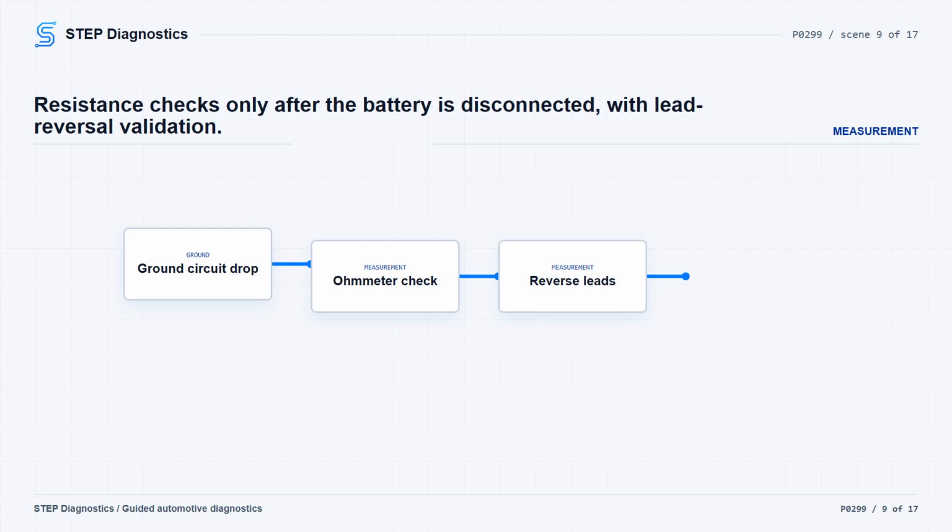Use an ohm meter accurately only if the battery has been disconnected. For most small diameter, 18 gauge and smaller, wires, expect less than 2 ohms. For most wiring harness circuits, also expect less than 2 ohms. A standard DMM ohmmeter's low resistance resolution is approximately 0.1 ohm, so its accurate use is limited to circuits carrying less than approximately 5 amperes.